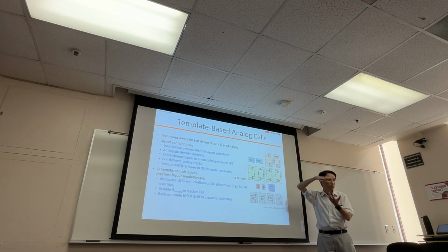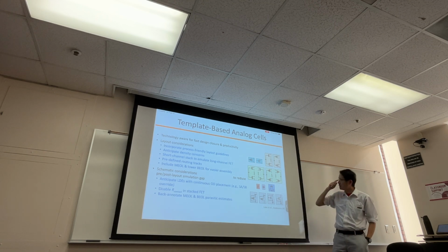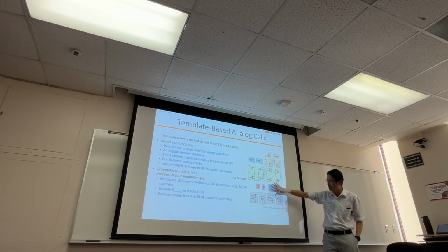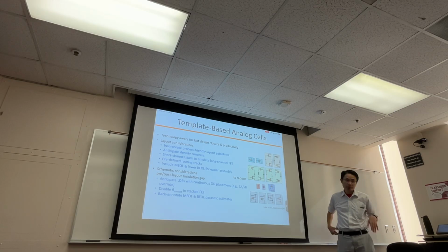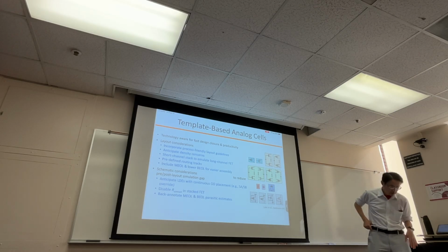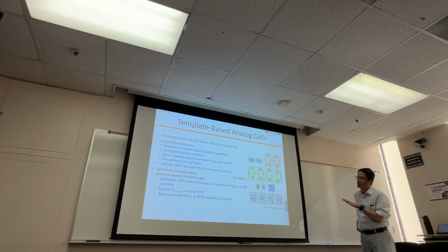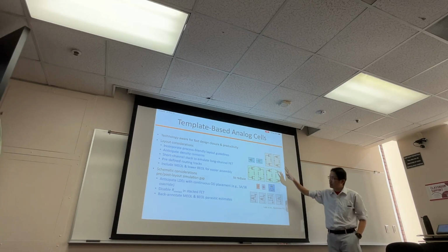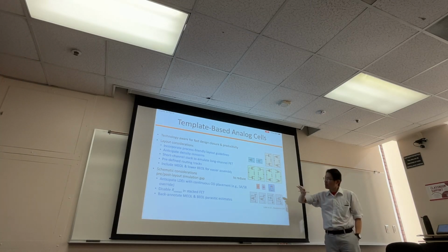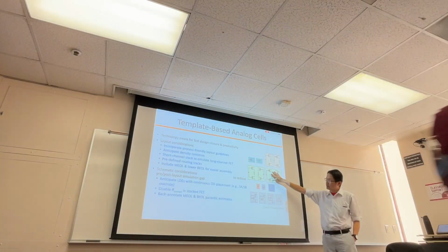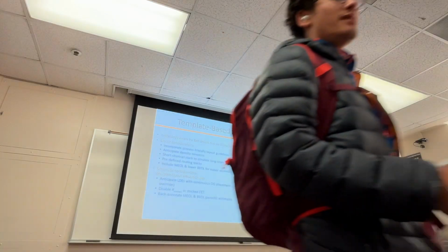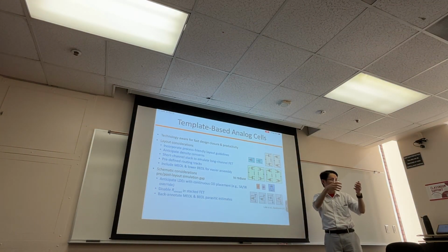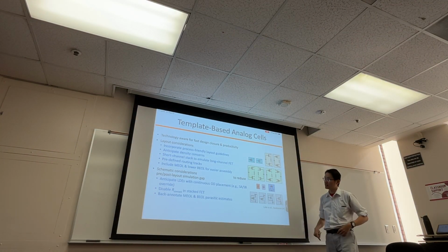So in order to increase the channel length, and you have NMOS, PMOS, and then even if you say, okay, I need a diode-connected device, you would just create a lot of templates. Okay, and those templates, what you need to do is, whenever you need to use this kind of device, you just copy and paste. Okay, so it's pretty much like playing Lego. You just cut them, you stack them, things like that.